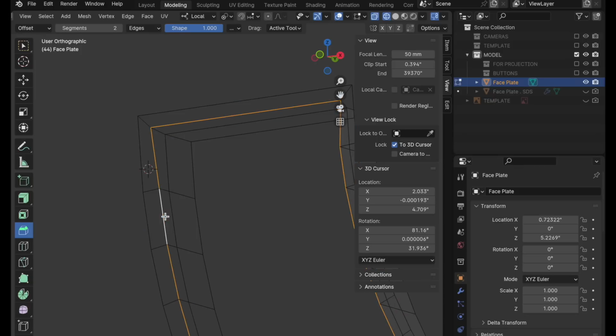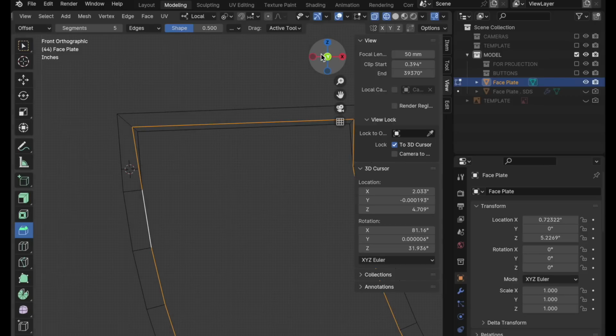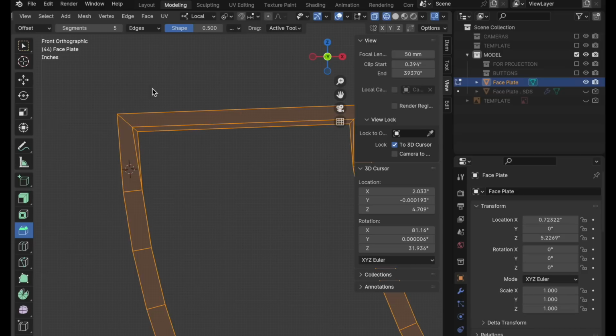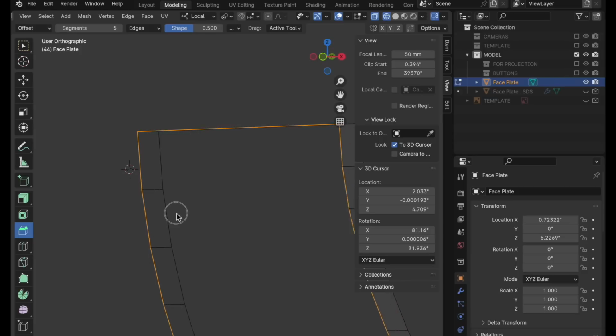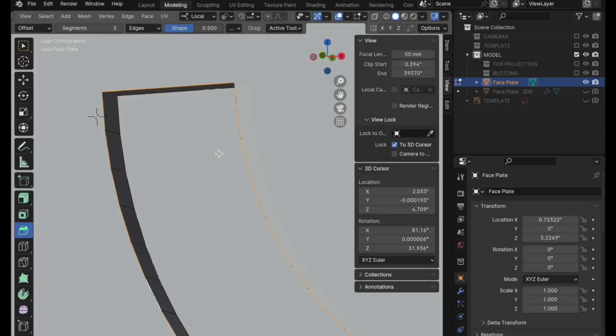So let's double click this corner loop. Let's switch this back over to maybe like a 5.5 configuration. Let's come into the front, and when we try and bevel it, you see how it's down here, it's what I like, but it's now overshooting. And so the algorithm is producing something that's a little bit wonky. So we're going to undo this, and we're going to back up, and I'm going to approach this a little bit different. Let's come back into shaded, make sure we're in face mode.